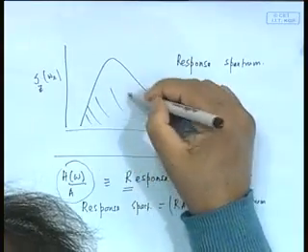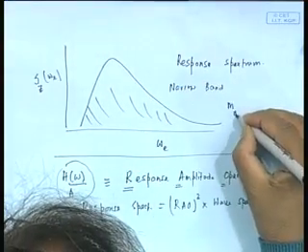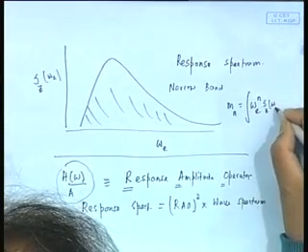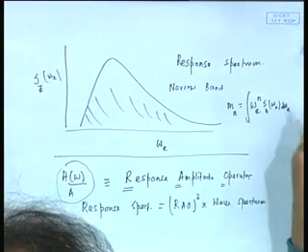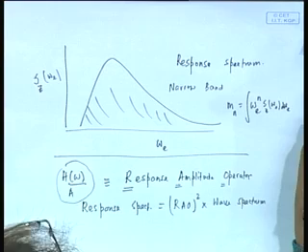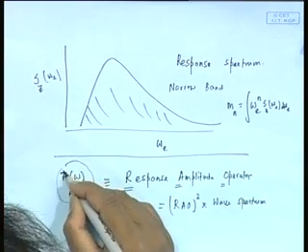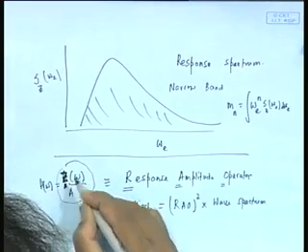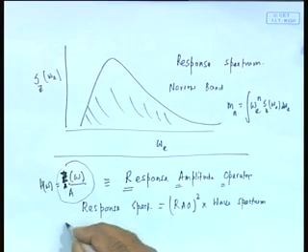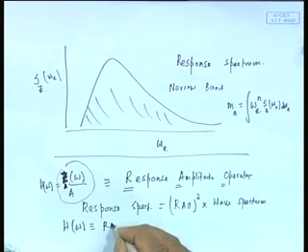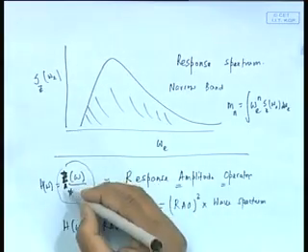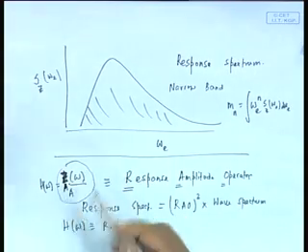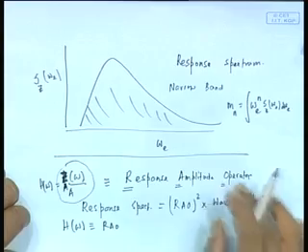So, if I have this, then what happens? Let me look at the area under that. Let me call this Mn. Yes, it is H, absolutely, I am sorry. The ratio of Z amplitude to wave amplitude as a function of omega, that output by input part, which I call H omega, is basically RAO in our case.